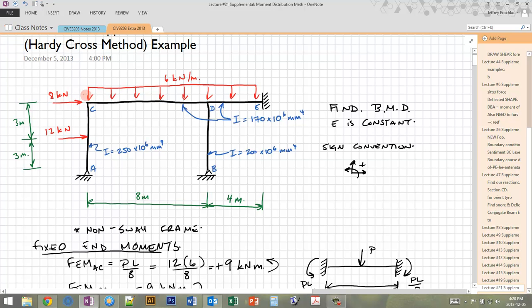that are in that joint. So for example, if I had a moment at point C, which I am going to do in my moment distribution as part of the process of equilibrating that joint, how much of that moment is going to be taken by CD and how much is going to be taken by CA? And again, that's going to be based on the relative stiffness. Higher stiffness elements take more load. Stiffness attracts load. Good thing to remember in general.